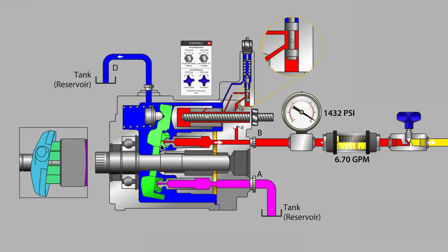Those shoes are floating on the swash plate. There is also the piston ball, which is crimped into place on the piston shoe. There's a minor amount of clearance there. And all of the cylinder barrel on its porting face is rotating against a porting plate inside the piston pump as well. So there's a rotating piece and a stationary piece. And that porting plate is a minor clearance as well. So many clearances, all of them I said they were minor clearances, but if we add them all together, they make up a fairly substantial cross-section of orifice opening inside the pump.